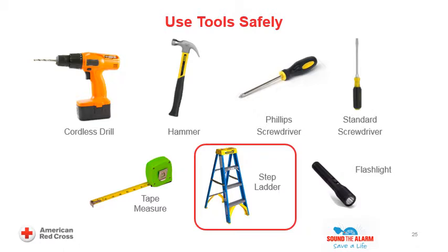Do not exceed the maximum load rating of a ladder. Step ladders are meant for one person. Do not place a ladder on boxes, barrels, or other unstable bases to obtain additional height. Do not use a self-supporting ladder, for example a step ladder, as a single ladder or in a partially closed position. Always open the stepladder spreaders and shelf fully and lock the braces. Do not move or shift a ladder while a person or equipment is on the ladder. Always maintain 3-point contact, two hands and a foot or two feet and a hand, on the ladder when climbing. Keep your body near the middle of the step and always face the ladder while climbing.